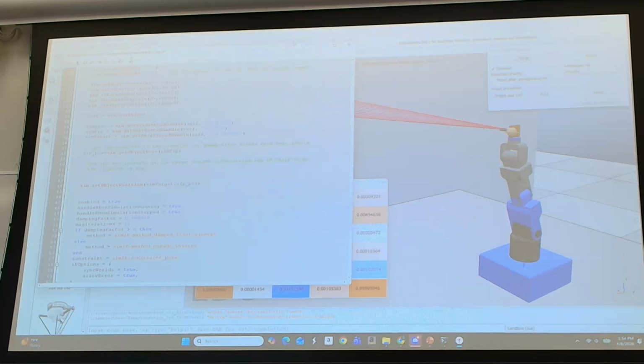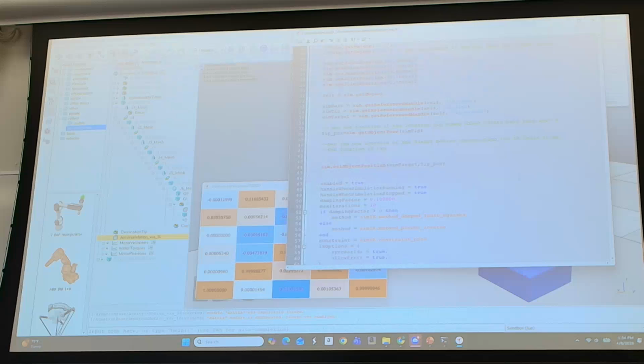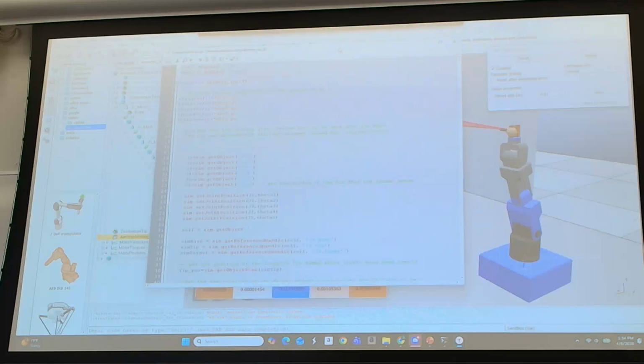So what you do is you pick the tip, the dummy to the base. So you pick this last joint from here down to here, and then you tell it to find the inverse kinematics. So go through the modules, and it's under kinematics, and then we do the inverse kinematics generator. So that's how it generates the scripts, and then you modify it from there. I thought I also had... I'll find out where it went. I thought I had one that also was showing the loads on each one, the torque.